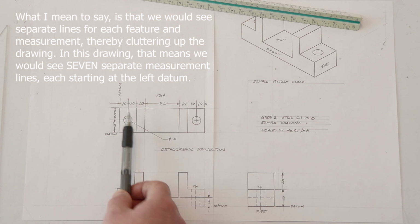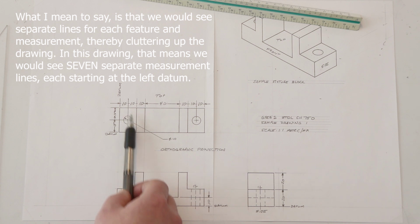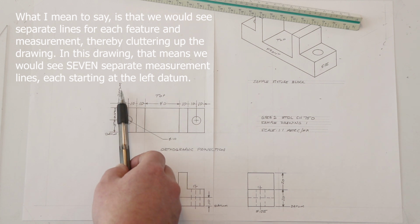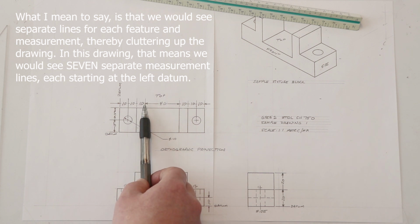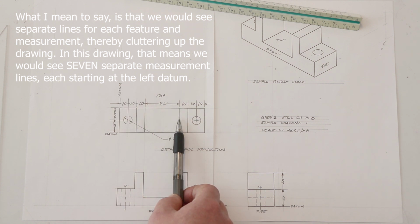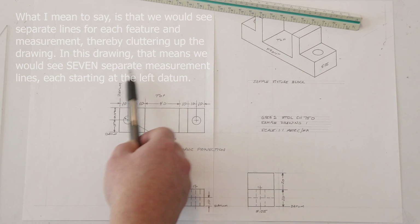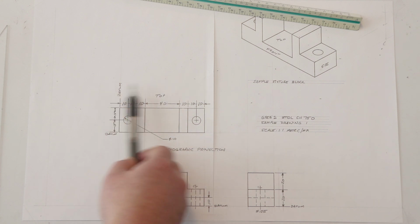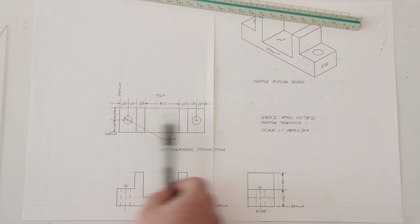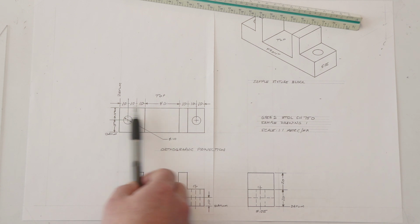So in this case, if we were going to have that visible to us, we would see 10 millimeters to the center of the bolt hole, 20 more millimeters over to the edge of the shoulder, and then another line noting 30 millimeters, and then another line noting 40 millimeters to the next edge of that shoulder. So you can see we would have many lines stacking up here on top of our drawing that would show a whole bunch of locations when it's more efficient and cleaner to list them this way.